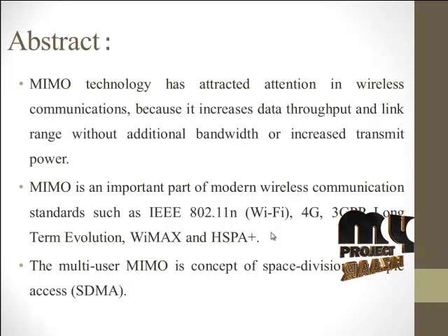Our implementation on USRP N200 shows that traditional rate adaptation does not deliver the gains of MIMO wireless LANs and can interact negatively with multi-user MIMO, leading to low throughput. In contrast, enabling multi-user MIMO with Turbo Rate provides a mean throughput gain of 1.7x and 2.3x for 2-antenna and 3-antenna access points respectively.